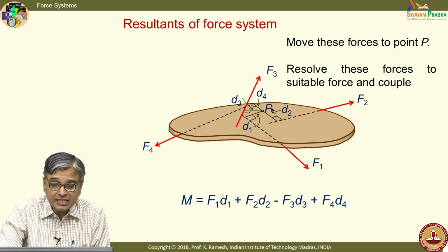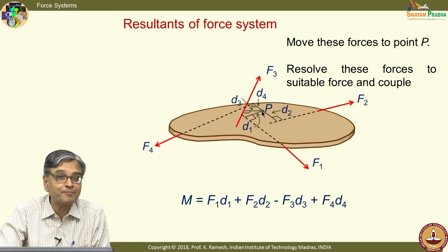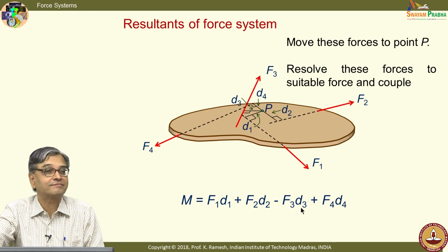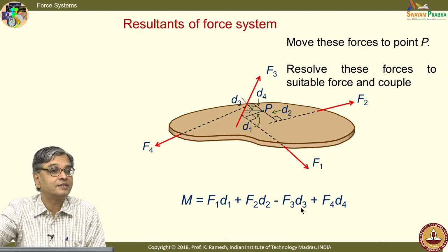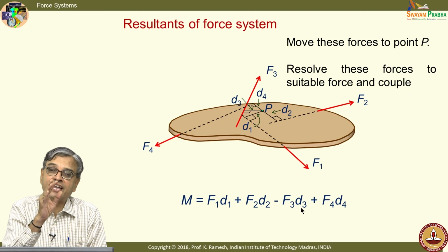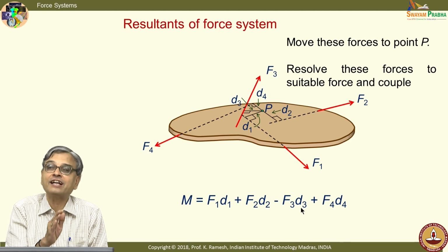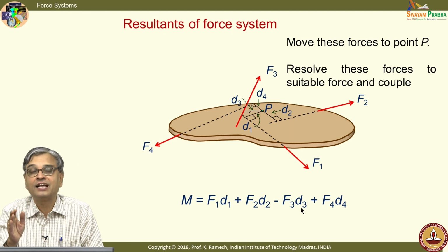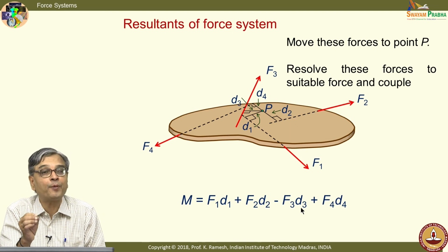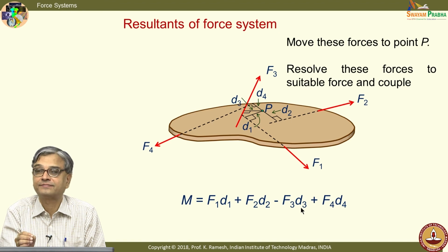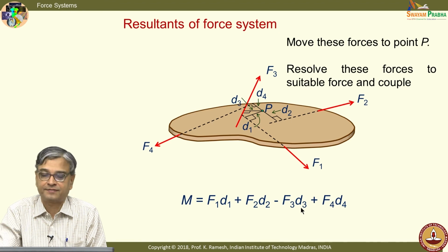Then with these moments, I can move these forces to this point. I cannot simply take a force and move it to that point. Then it is a different problem. If I have to maintain the same external effects of the original force, I have to recognize that when I translate, I should put in the appropriate couple components. Fine.